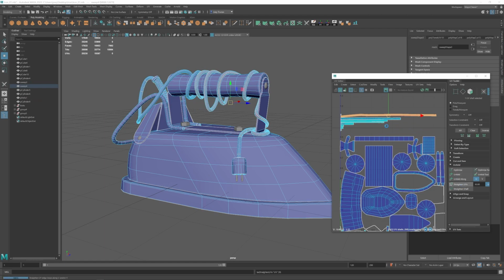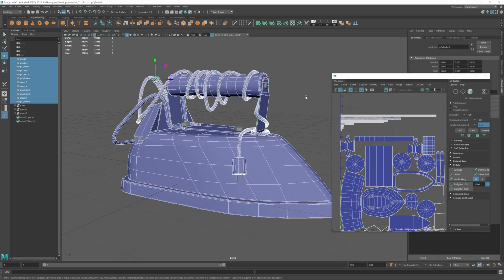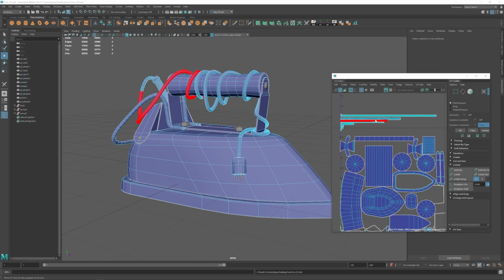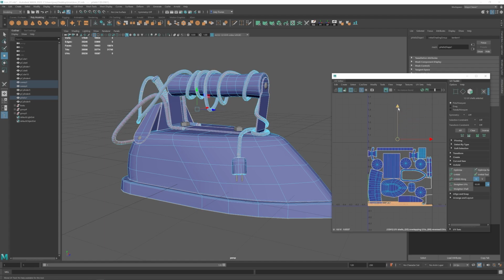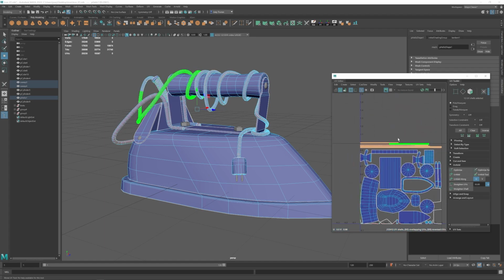So it's a really good habit to straighten your UV shells when you can, and that top sweep mesh is clearly bent. So we're going to go over to our UV toolkit. Under the Unfold drop-down menu, we're going to go select Straighten UVs. And that's just basically going to straighten that shell so it's nice and straight. And I'm actually really quickly going to go ahead and straighten all of these shells. And now that those shells are all straight, I can fit them much better on my UV map.